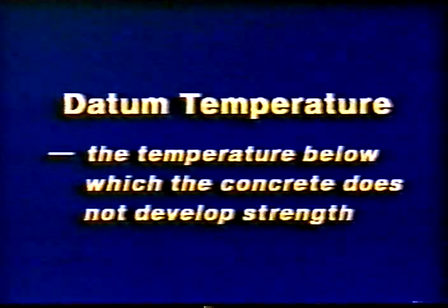The datum temperature used in calculating maturity is experimentally determined for individual mixes. It is the temperature below which the concrete does not develop strength.